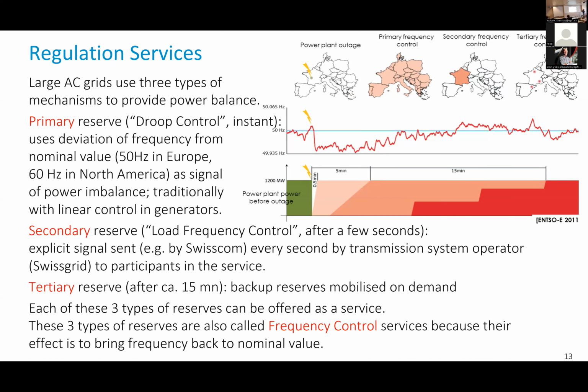You have a nuclear plant that is not working. So the secondary reserve will work for some time. The secondary reserve by grid code should be activable within minutes and should last for 1 to a few hours, but not more. So there must be a replacement for this power plant that is no longer working. This is called a tertiary reserve. Those are standby devices that can be activated when they are needed, but that may require some time.